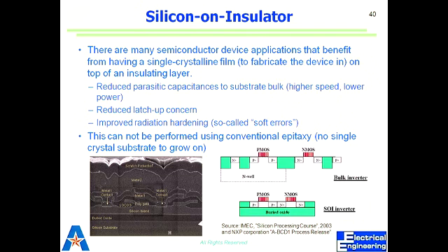We get a type of wafers called silicon on insulator wafers. Of course, we know one way of making SOI is implantation, right? You implant oxygen species, let them go a certain depth, activate them. You have silicon dioxide buried. Or you can oxidize silicon wafers and bond them.